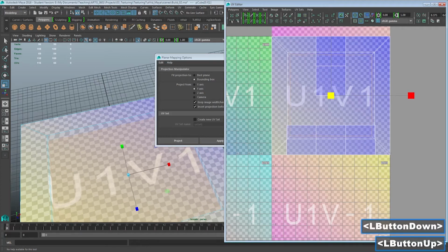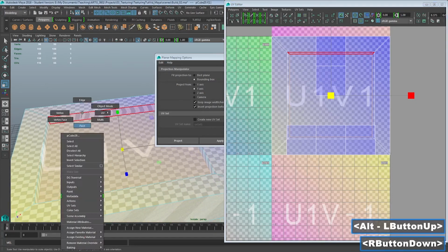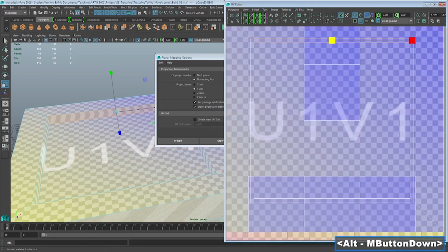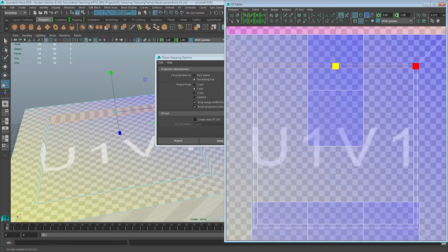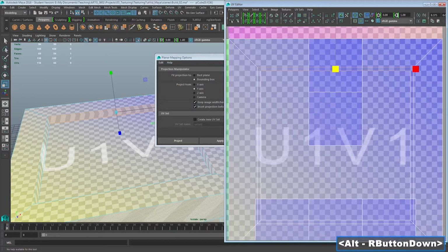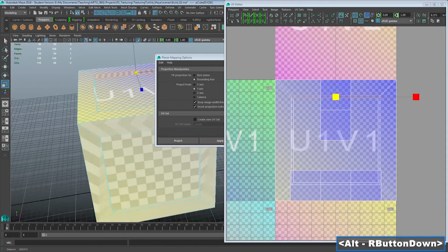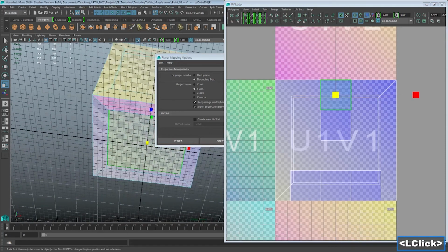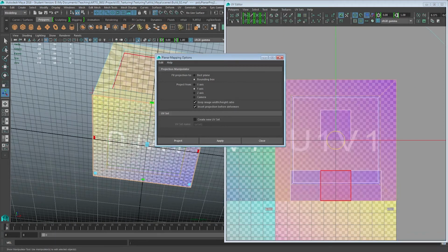Now, there is some distortion that is occurring based on this layout because these square faces here are angled in my UV editor. A way that this can be remedied is by making my UV layout more involved, but for now, given that this will eventually have just a wood grain across it, this level of UV layout will be sufficient for what we'll be doing. As I go on, I will be taking other sections of my model and applying a similar treatment to the projection.